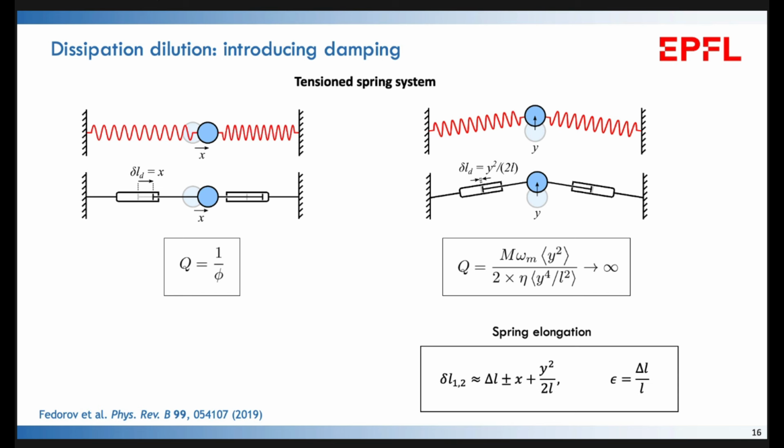Now, one short explanation, I think it's still very interesting to think about the concept we're using here. I want to show a very simple toy model that's been developed by Gareth Steele with Sergei Fedorov, that really helps understand how this works. If you have a typical spring mass model, you can model the spring being lossy, so it's a damper, and then your quality factor is the inverse loss angle, and this is just the retardation between stress and strain in the spring constant that's assumed to be complex here.